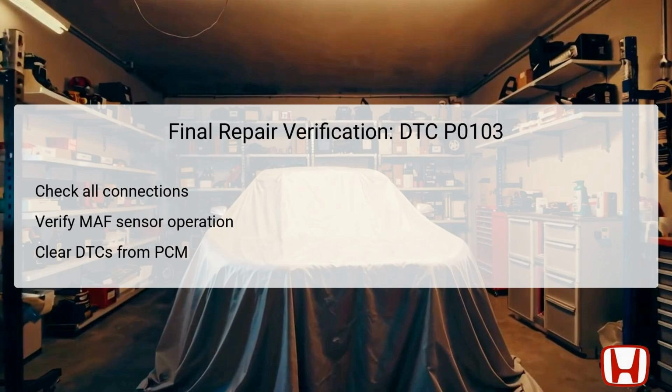Utilizing the Honda Diagnostic System, HDS, check the readings and ensure they are within an acceptable range. Once verified, clear any diagnostic trouble codes, DTCs, from the PCM. Performing a road test will help confirm that the repair has resolved the issue and ensure that no new codes appear. This final verification guarantees that the repair was successful and that the vehicle is functioning properly.